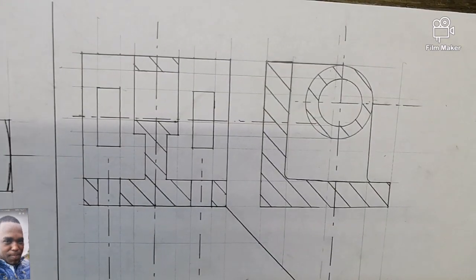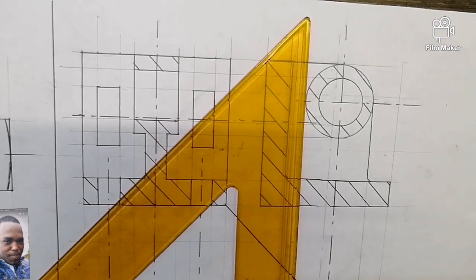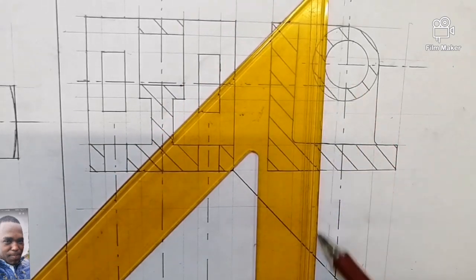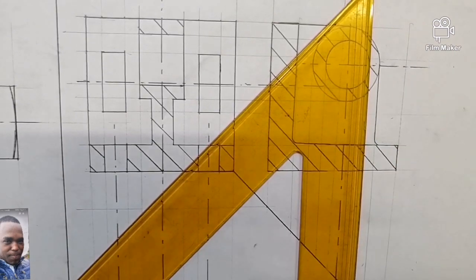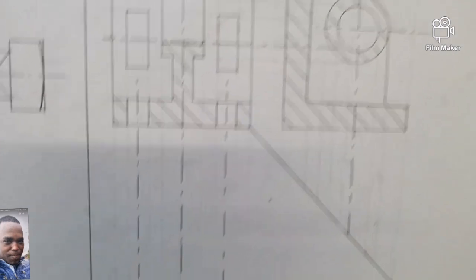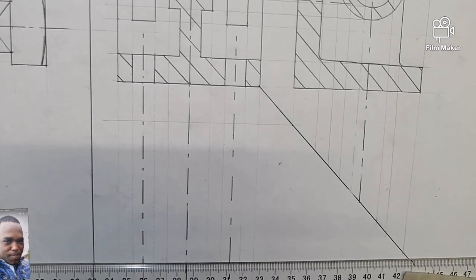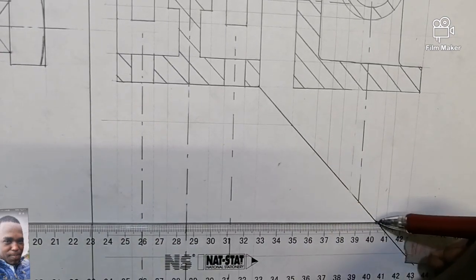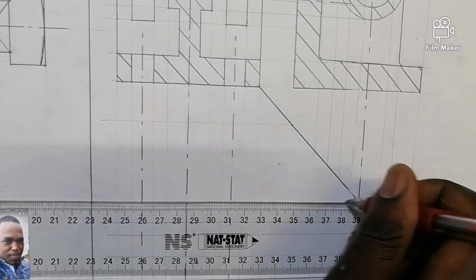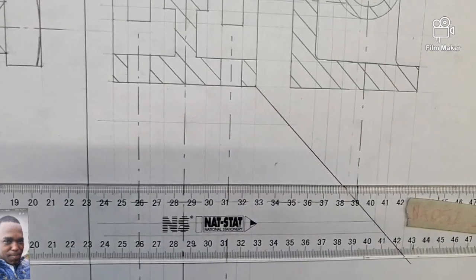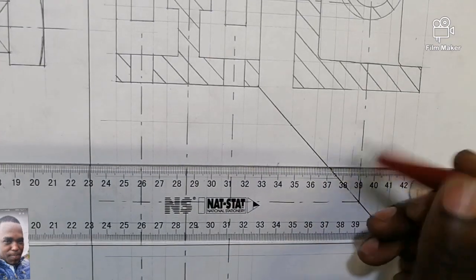So you must take all the points that are behaving horizontal, vertical from your left view. Once they touch the line of 45, then you stop. This one, take it, stop. This one, take it, stop. This one we took it, this one we took it. Once they touch this line, then they go horizontal left hand like this. Faint. We don't draw, we don't take dimension when we are now drawing the third view. This one is the center, is going to remain as solid center line.